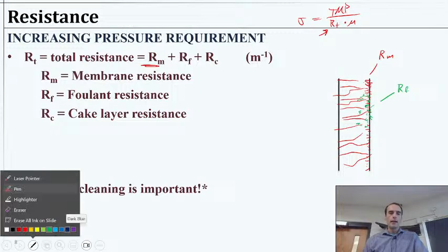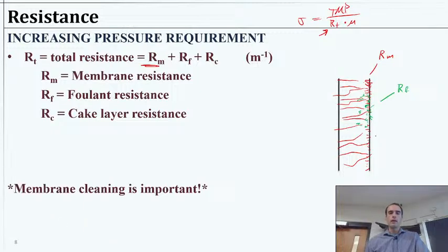And then lastly, we would have a cake layer forming, and I'm just going to draw it a little lower to distinguish it. These would all happen kind of all over, but I'm just going to draw it this way. So after you get some of that on there, we already mentioned this fouling layer would start blocking enough materials that you start having an accumulation of physical layers on top of the membrane, so the water has to go through that.